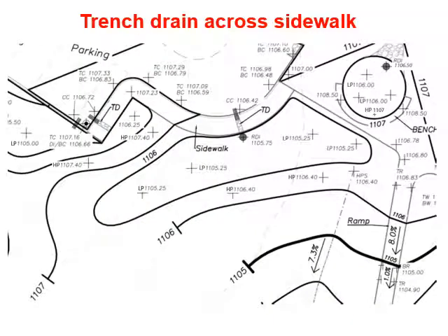And again, you're going to want to refer back to this drawing to get all this information. So here are the curb cuts. We only have one spot elevation and two little leaders that tell us that those curb cuts are at the same elevation. We have the trench drain labeled. We have the low points labeled. We have the high points labeled. And of course, we have the elevation for the drop inlet. And I want you to note when we look at that, the elevation for the drop inlet is the same as the elevation for the bottom of curb.